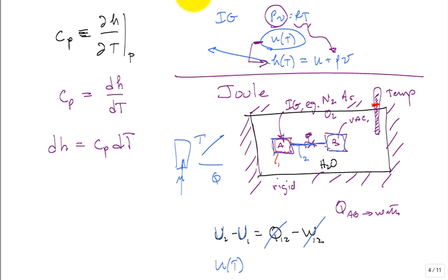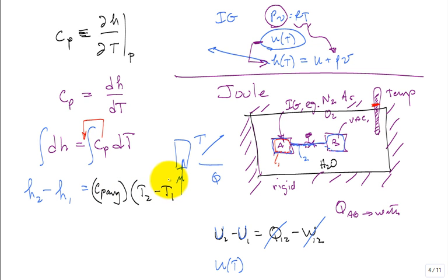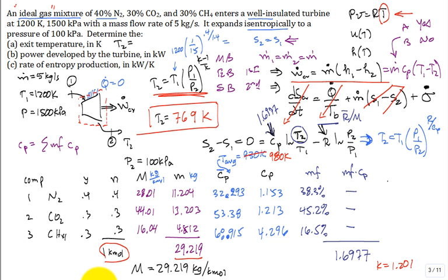And if you have an interest in calculating the final enthalpy minus the initial enthalpy, it's the integral of C sub P dT. We don't like integrals as engineers. We like to make things very simple. So when in doubt, use an average specific heat over that temperature range times the temperature difference. Make sense? So go back to this.